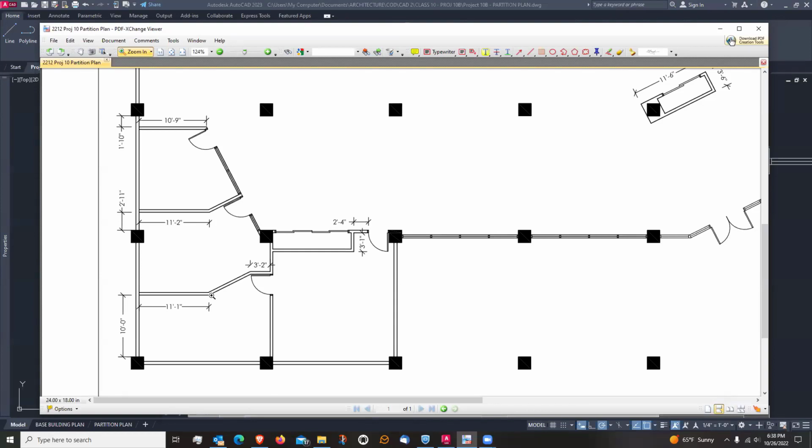So I know I have this wall and it's some length, but somewhere on that angled wall, this wall is going to intersect, and it's going to intersect exactly at 3 foot 2. Well, what I can do is, if I offset this line of this wall 3 foot 2 inches, I'll have a guideline that's out here 3 foot 2. And where that guideline hits this angled wall, bam, that is where my 3 foot 2 wall is going to be. In theory, let's see if this works.